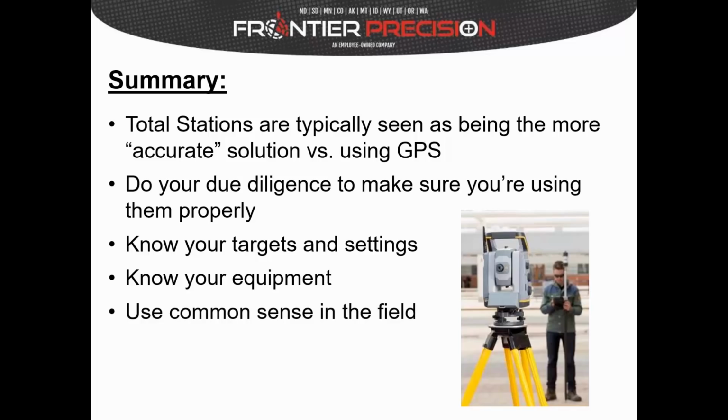Use common sense in the field, okay, especially when you encounter issues. Check your backsight residuals before you store them, things like that. Make sure you're set up on the right point. Make sure you have the right coordinate system selected. Make sure you're in the right job, things like that.